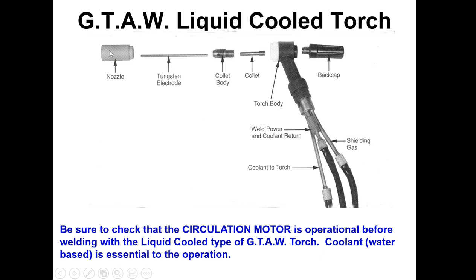And they will melt. If you use a nozzle that's too small and use a lot of current, you'll actually see the edges of the nozzle start to melt and liquefy. But the material here, we're looking at about 8,000 degrees to get it to melt. So that's quite high. The tungsten electrode, which is not consumable, does not belong in the weld, nor should it be. But if you use a tungsten that's too small for what the job should be, that tungsten will get liquefied and will drip into your puddle and cause you a world of hurt.